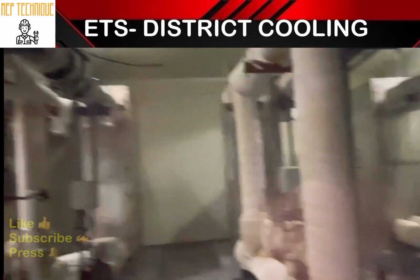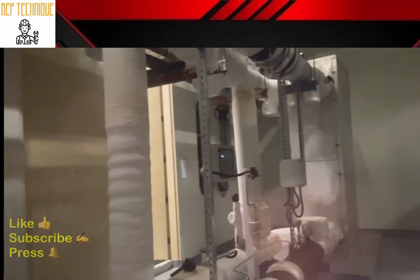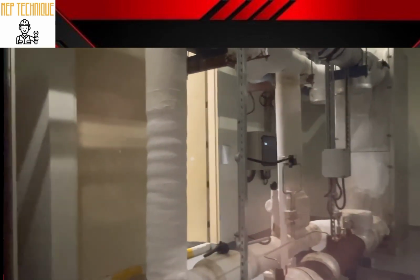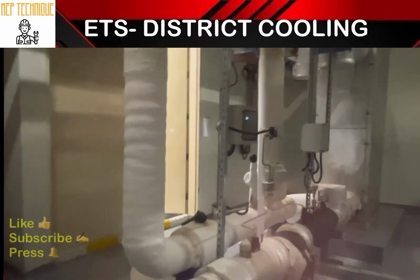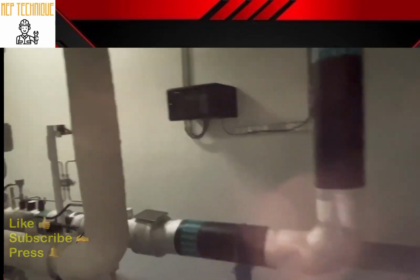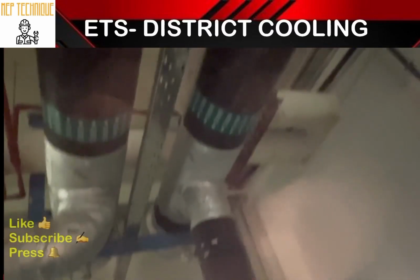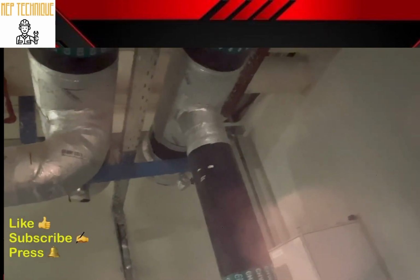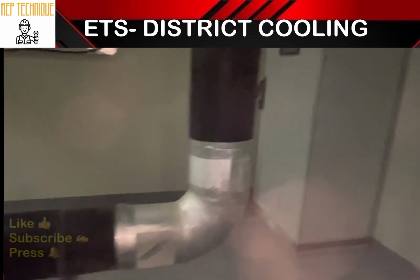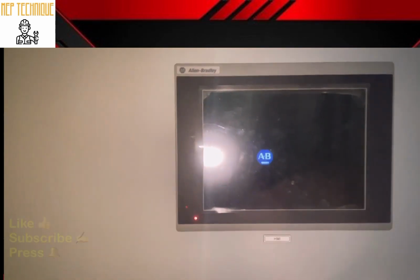Before going to the PLC, I would like to mention that our secondary circuit is connected with the secondary pump, and the pumps are operated by VFD, variable frequency drive. How does your VFD adjust the frequency? There is a DPT installed in the riser line, at the end of the riser. This DPT signals the PLC to increase and decrease the speed of the pump. So the motor frequency of the VFD is operated by the DPT, differential pressure transmitter.